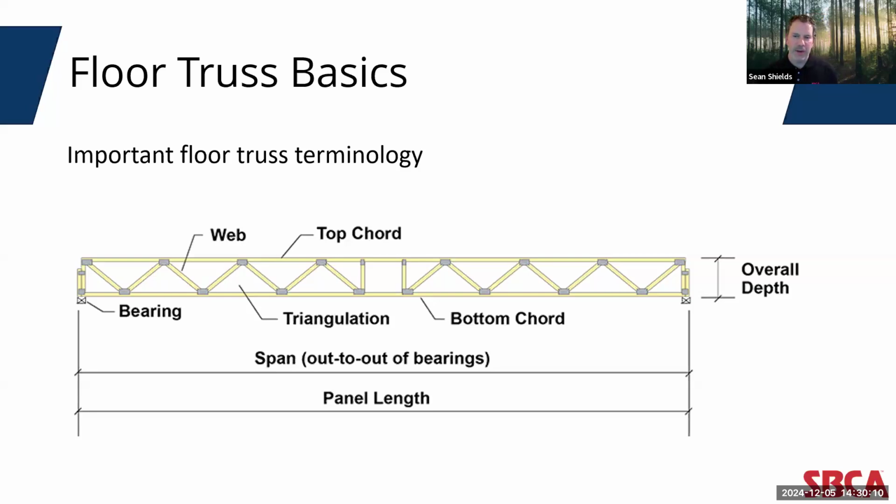Another floor truss configuration is the top chord bearing floor truss. In that configuration, the top chord of the truss is responsible for transferring forces to the bearings. The top chord then carries the combined tension and bending stresses.